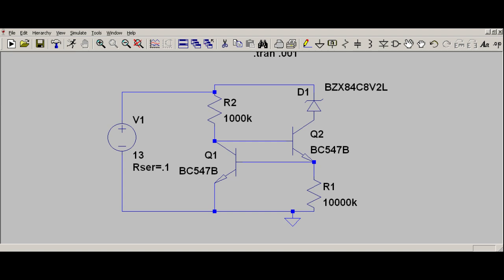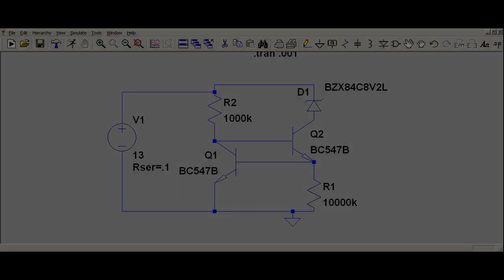This circuit will try to always sink the same current value regardless of the actual component we place as Q2 collector load. So if we put different zener diodes on Q2 collector, we can measure what voltage is needed on any particular zener to make it pass the same 95 nanoamperes current this circuit is made to sink. Of course, the higher the voltage we'll measure, the lower will be the leakage of that zener diode.